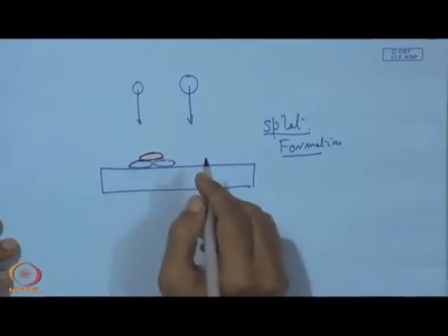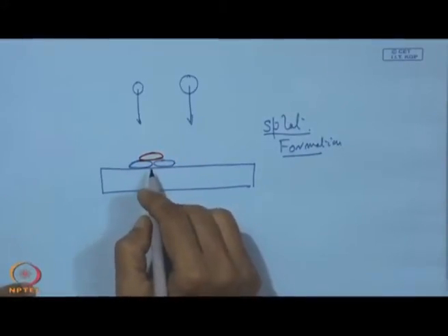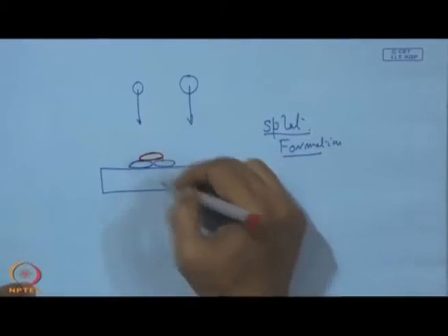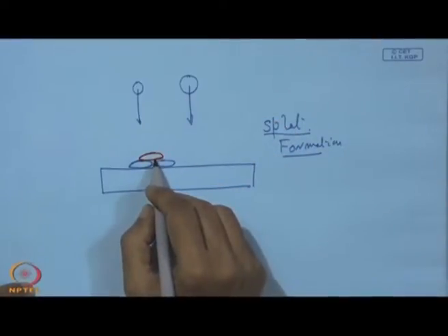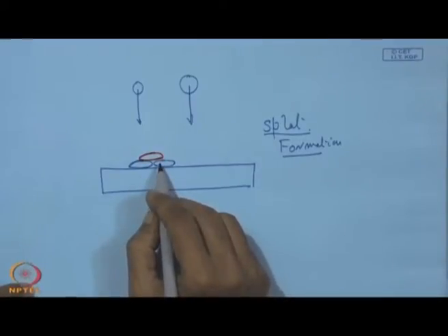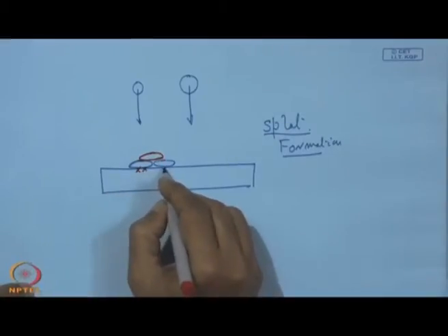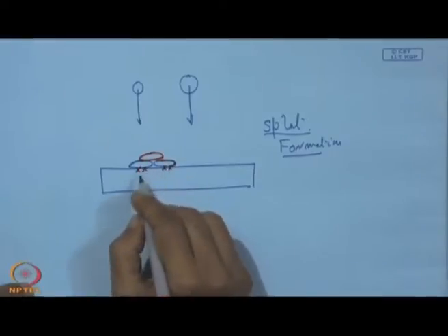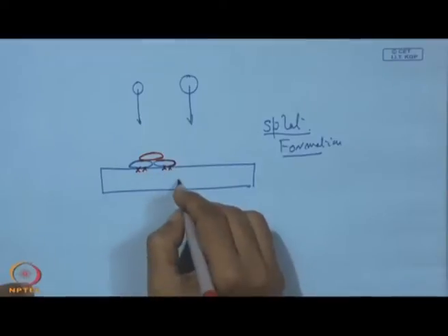So, this way it is going to build up the whole thing, and then we are going to get a well adherent coating. So, in this process the material first impinges on the surface, followed by condensation, solidification, and then adhering either to the substrate surface or to the original surface, which is already solidified over the substrate.